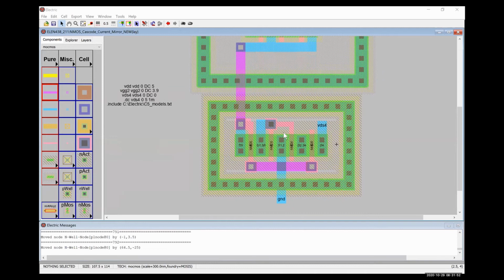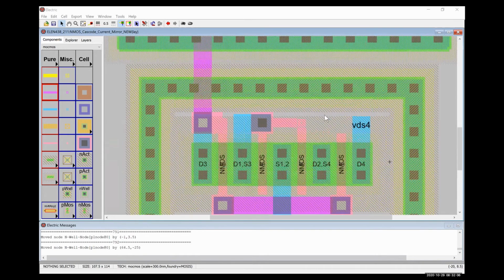Yeah, so down here on our Nmos transistor bit, it's not giving us that error, even though there's a little bit of gap here. You can see there's nothing in here, but it's because the substrate is implicitly P-well. So it's considering that this region right here is P-well. This thing on the side of the ground ring is P-well, and although it doesn't show it, this is also P-well, so that's why we're not getting that same notch error.